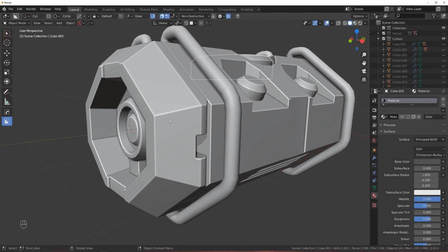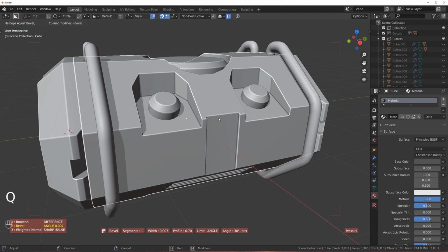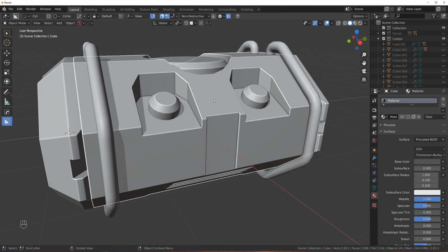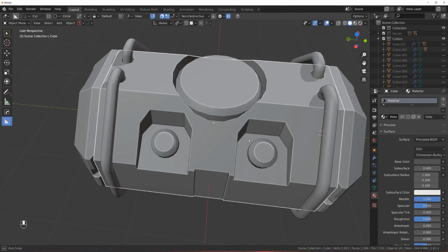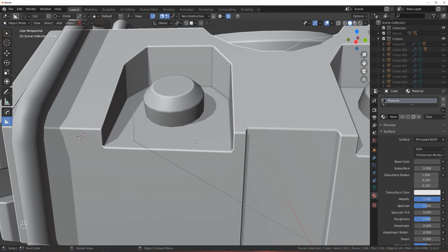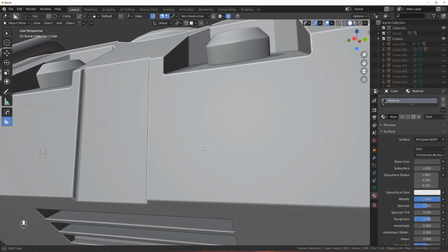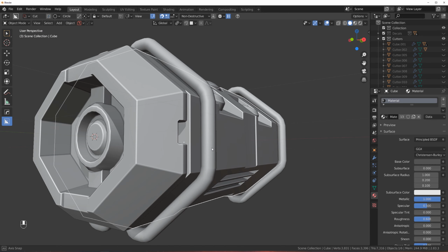And you see now, if I actually increase the count of bevels to 3, so I went to the bevel and went to 3, watch what happens to the count of geo. Went from 7 to 10. So this whole mesh could be either 12 or 7. See my point? So that's how you bevel. You bevel it with one segment, and then you literally drop weighted normals, and you're done. That's all you need to do.